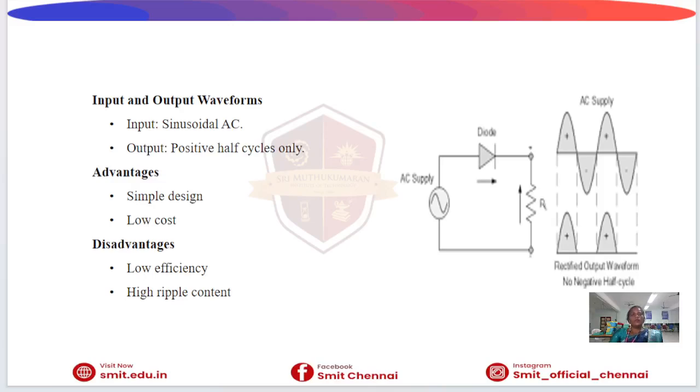The advantages of a half-wave rectifier include simple design, fewer components and low cost. However, it has low efficiency, poor transformer utilization and high ripple content. Due to these drawbacks, it is mainly used in low power applications and educational demonstration.